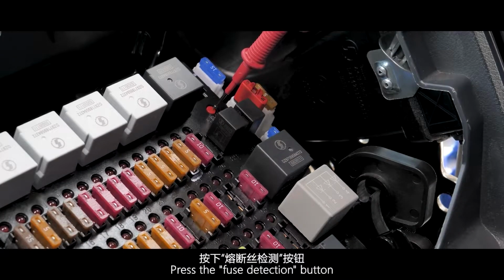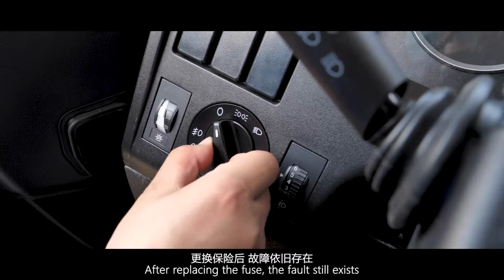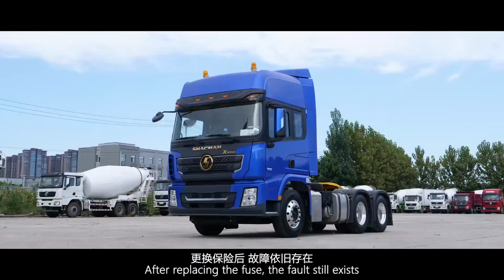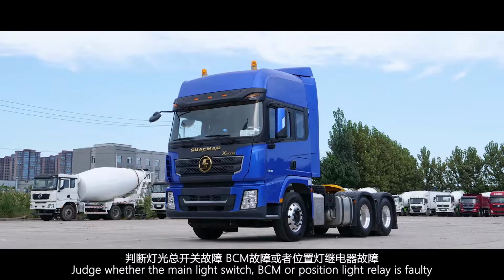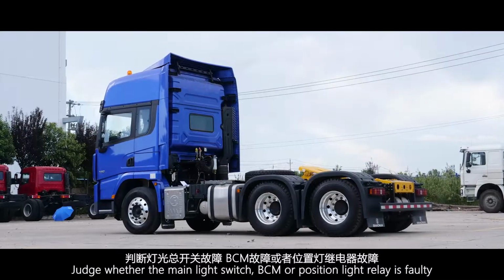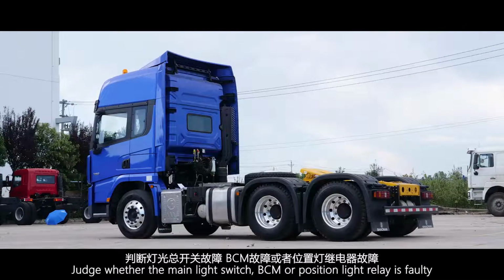Press the fuse detection button. The indicator light above the number 63 fuse is not on. After replacing the fuse, the fault still exists. Judge whether the main light switch, BCM, or position light relay is faulty.